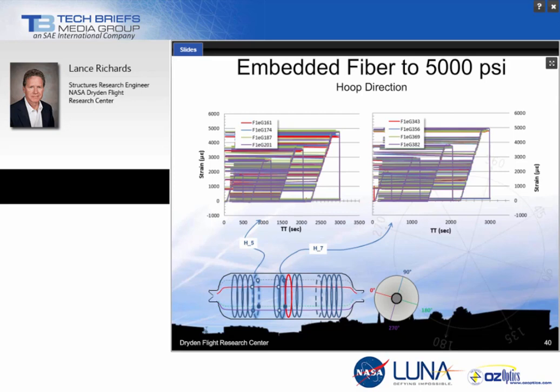And what was hopefully being shown here is that the horizontal lines are an aberration. What hopefully you can make out are the pressure cycles as we successively increase the pressure from one load condition to another. And we are showing very good correlation between the embedded and the surface-mounted sensors, which isn't the same thing if you were to go axially or in any off-axis directions. We end up getting some measurements that we've now begun to understand and how to correct for.